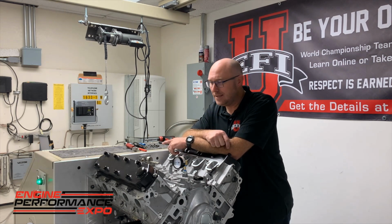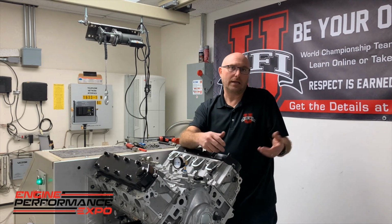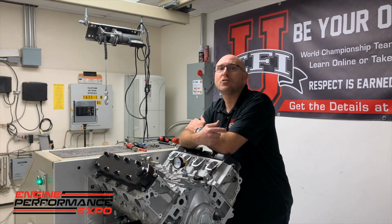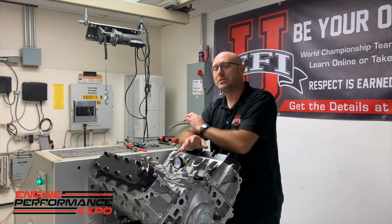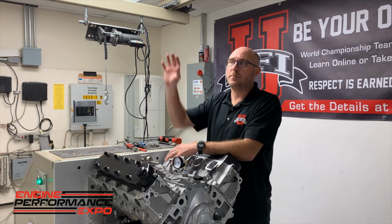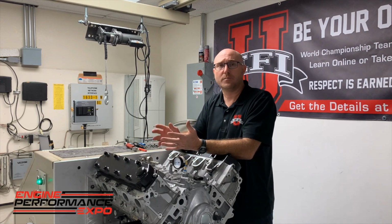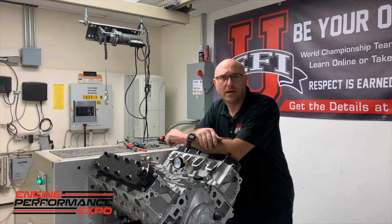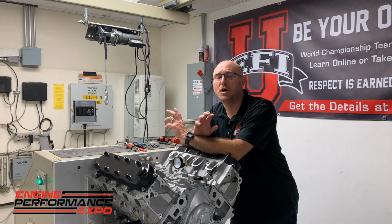But honestly, if it spits a valve out, it falls down into the engine, and we go in there and get it and clean it off, and most of the time you can put it back in because it didn't crash into a piston like it would have if we skipped this step and we took that $60,000 or $80,000 or $100,000 engine and we just assembled it and put it on the dyno. Then what happens, we run it on the dyno, if it drops a valve or breaks a rocker arm or whatever, it's catastrophic.